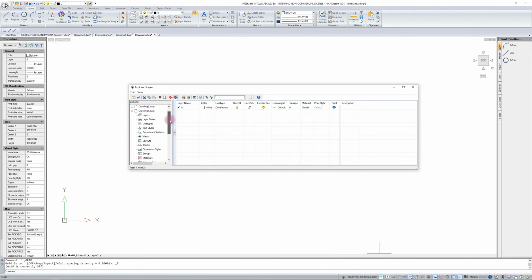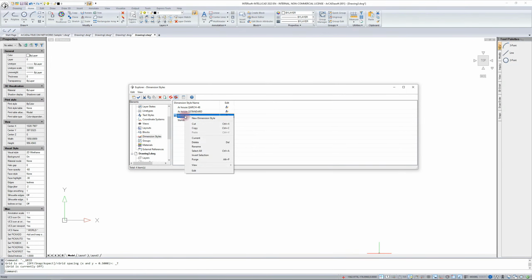That is a blank drawing on which, if we're talking about, for example, dimensioning, I'll take the dimensioning now from the project on which we've already dimensioned the drawing. These dimensions I'll just select for myself, copy them, and transfer them into my new drawing with paste. And I have the dimension.